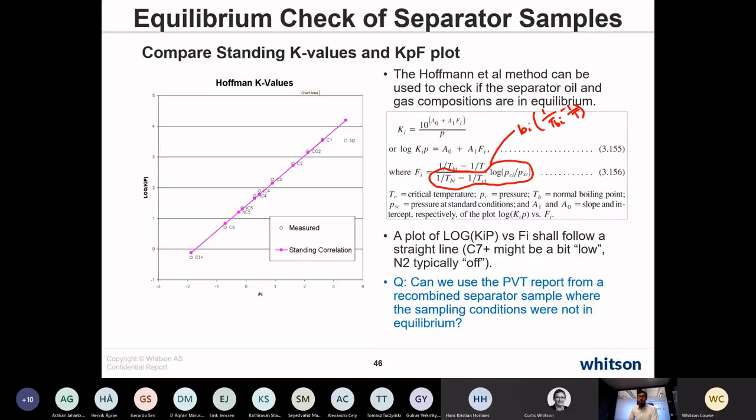So if we have good quality PVT data, for example, if we collected samples, separator oil, separator gas, they were not in equilibrium, we recombined those samples to calculate the well stream, and then we did, for example, CCE or CVD and DLE and separator test, and all those experiments done in the lab were very good quality PVT data measured on the well stream composition. On that well stream composition, we should be using all that data for the EOS model development.